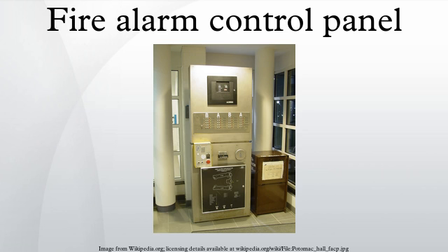Smaller panels could be set up in one of two ways. Most of the time, the panel would only have one zone, and therefore, only one code. Common one-zone codes were 4-4-0 and 17-0-0. Alternatively, the panel could be made with no code wheels, using only what was called the gong relay.